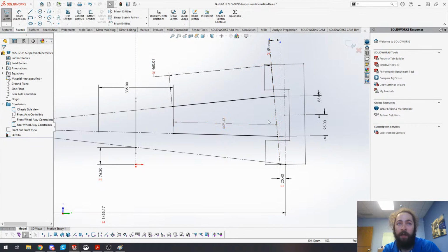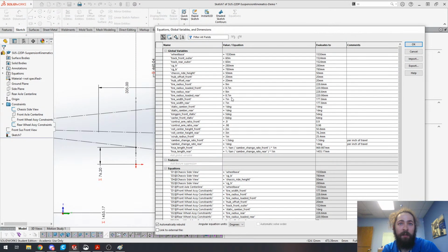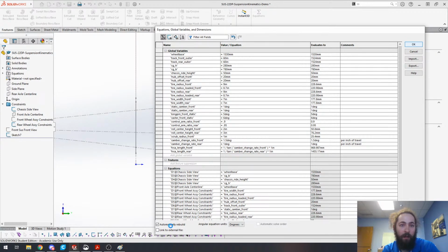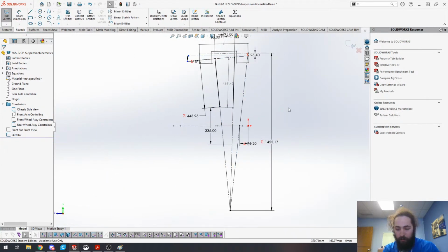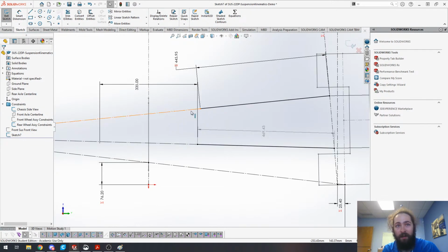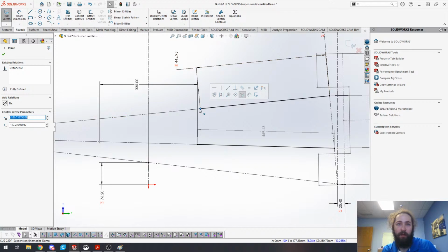And actually, because of that kingpin angle and how steep we had this set, I might adjust this to 0.95 and say OK. The automatic rebuild checkbox down here is also pretty helpful. But basically what I saw there was that our upper control arm was going to be poking in further than this lower control arm. You could change that by just making this drive that point instead.